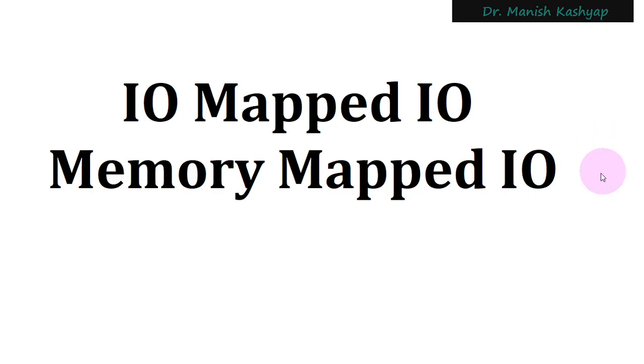So in case of memory mapped input output, the instructions that you were using for data transfer to and from memory were like STA, LDA, or maybe you were using the HL register as pointer. So you were using this LDA command, and you were supplying some address. So all those commands will be valid. Input output devices will be treated like memory elements only, because anyway they have been connected to memory locations. So those memory instructions will be sufficient to deal with those. However, in this input output mapped input output scheme, there are two separate instructions, IN and OUT, which will be used to transfer the data. So we will see that in programming also in today's session.